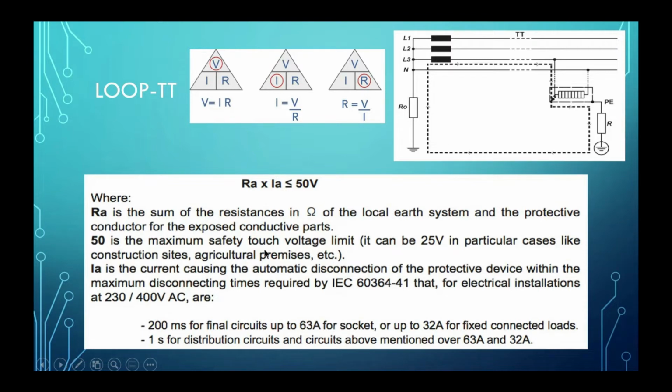Both of these normally have more moisture, more wet water, and this wet water may be dangerous to the electrical installation. And at construction sites, more electric tools are used.